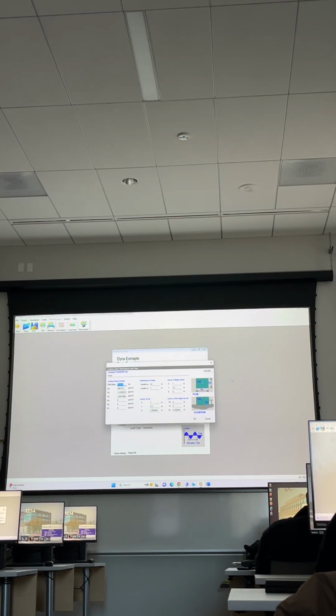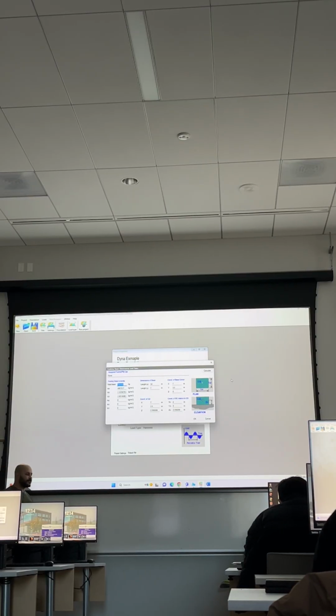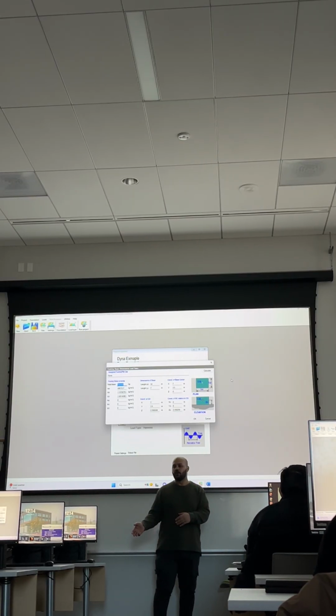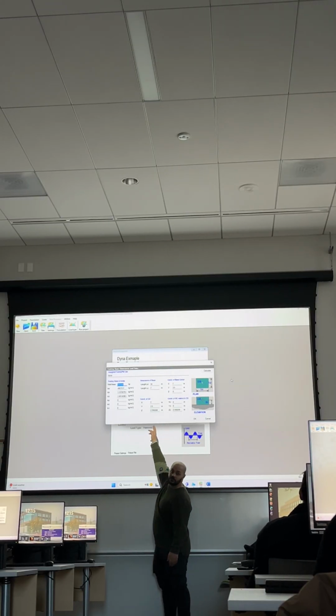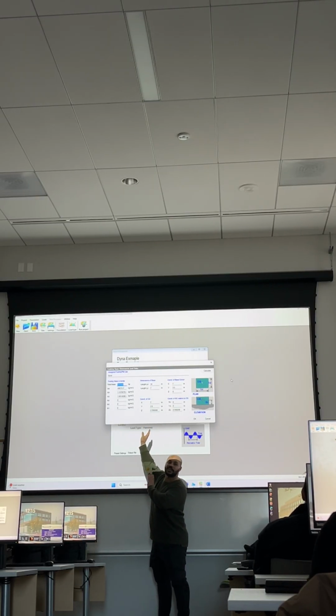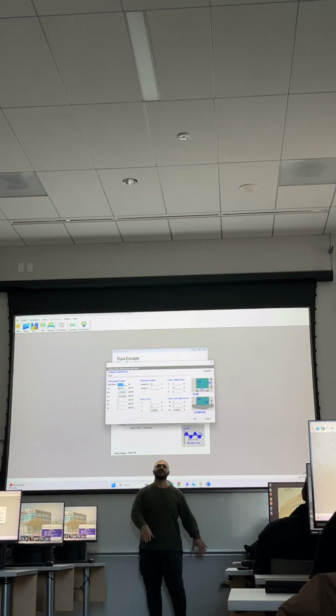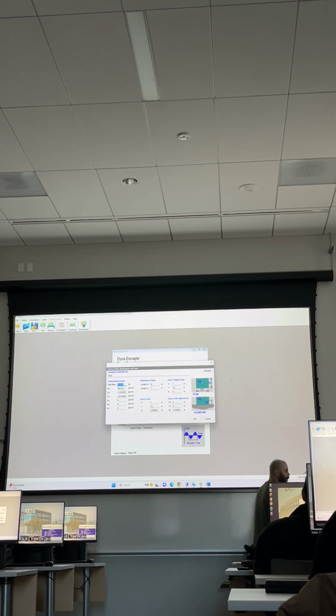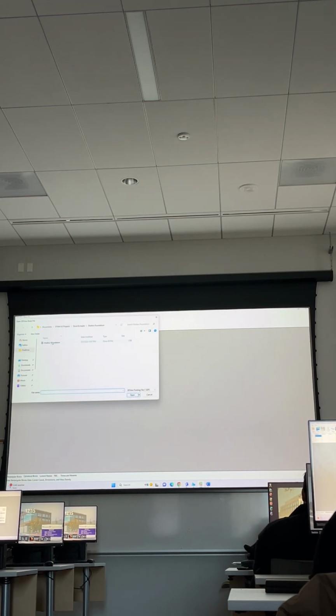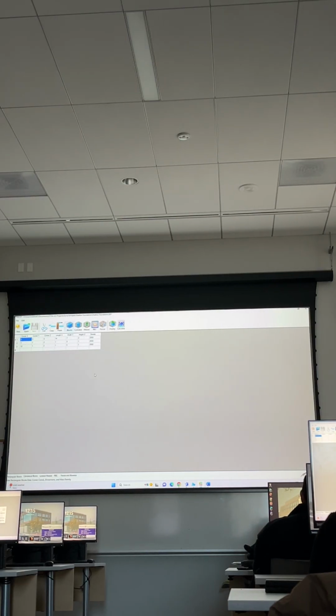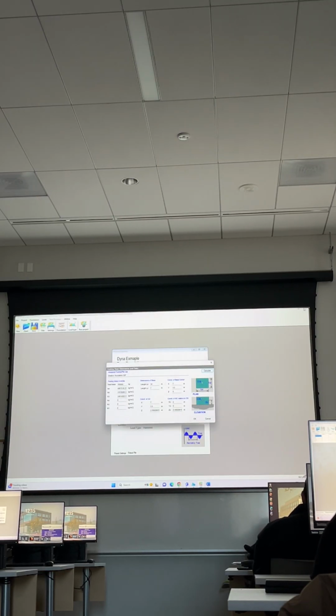For the pile cap, we have the same information as the shallow foundation. If you are studying the same foundation, but either it will be shallow or deep foundation, you don't have to change anything with that. This is the same foundation dimension, but this time we will define it as the pile cap. If you need to change something, it's okay. Press calculate and open again, and choose this foundation option and change whatever you want. The masses, RPM, forces, anything you want to choose, and then close.